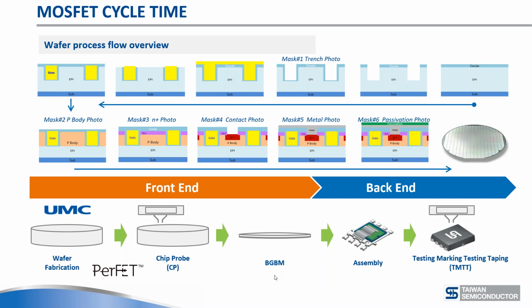It's UMC, one of the biggest foundries in the world. So when it comes to wafers and the amount of wafers available, we don't have such a bottleneck at all. These people make millions of wafers here. Gradually, as the lithography goes down and ICs become more and more complex and move to a smaller lithography, more and more capacity will become available in the nodes that we tend to use on MOSFETs, and that's 0.8 micron or 0.15 or somewhere in that area, 0.13 maybe in the future. So for us, the front end is actually well covered here.